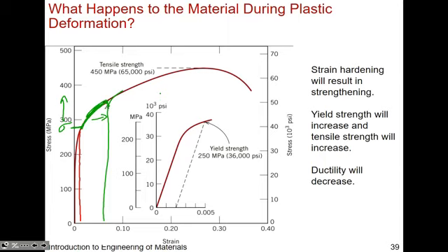Okay. So in this particular example, yes, you're introducing dislocation, you are plastically deforming by a little bit, but not to the extent that a machine could apply a load and neck a material. Certainly, the material really hasn't been necked. There's really no change, appreciable by the naked eye, in the cross-sectional area based on the applied load that Zachary applied. But if you do keep on increasing that load, increasing F, you will be able to get to a point where the material will start to neck.